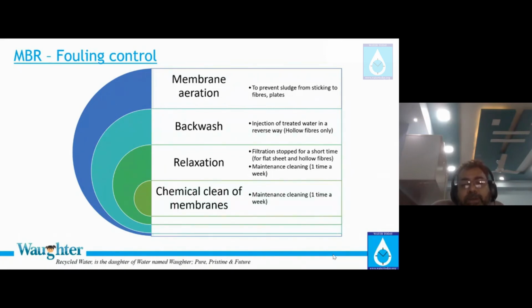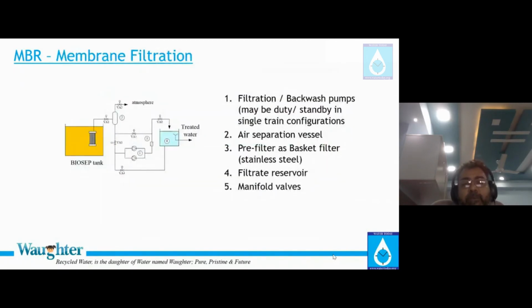Typically, we do it once in a week. Now, there are some membrane manufacturers who say they have flat sheet which you can backwash. Fine. But this is the general rule of design of MBR for fouling control. And these are some interesting slides.